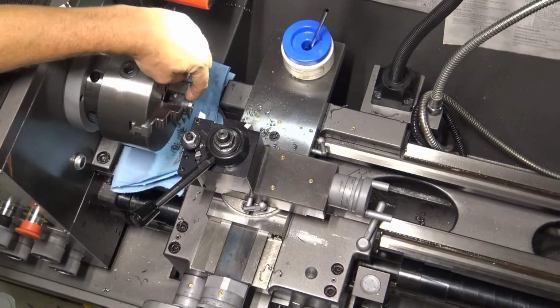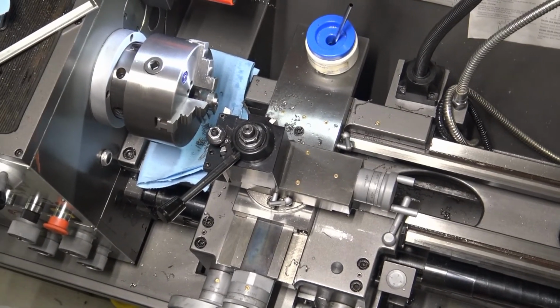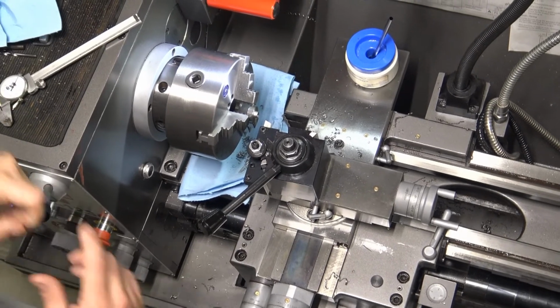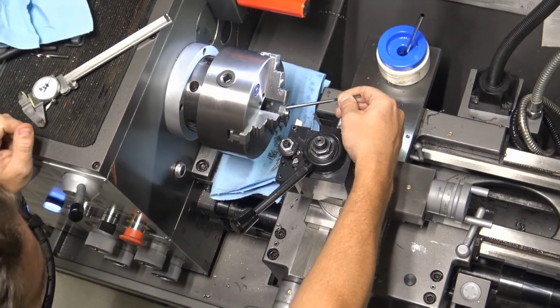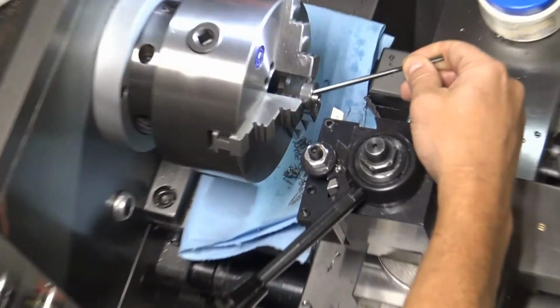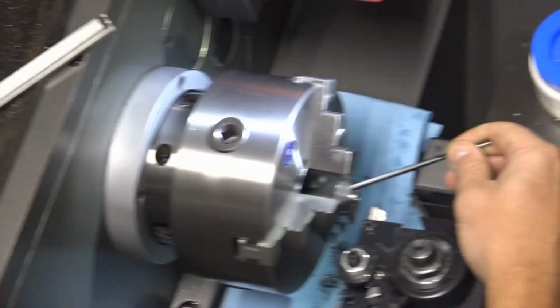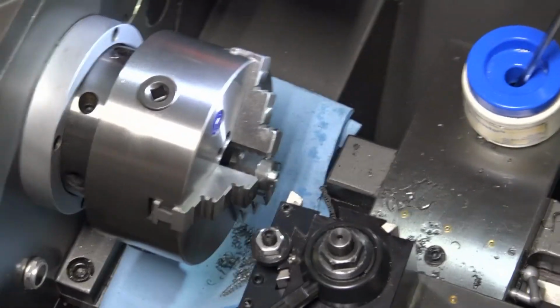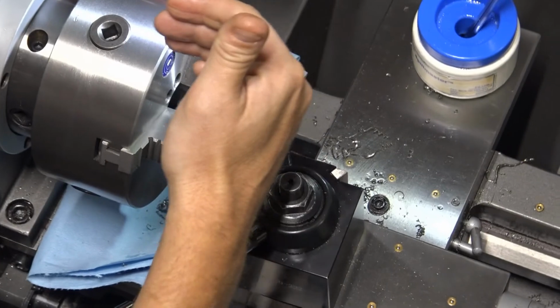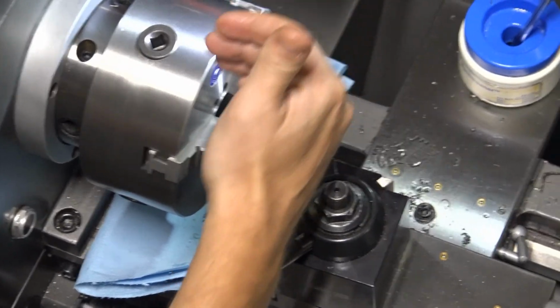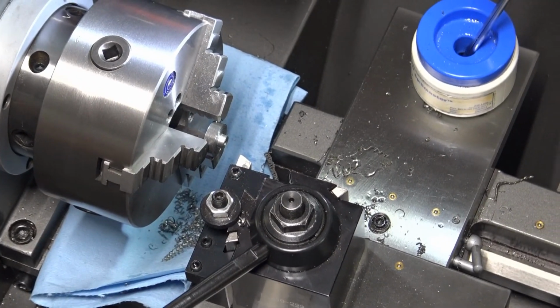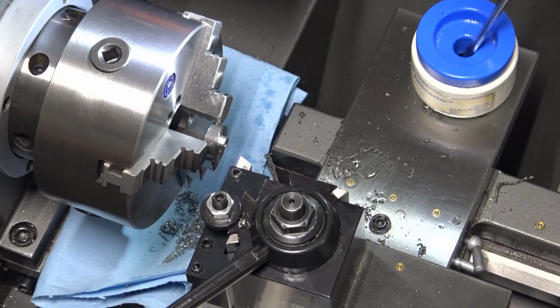It's going to be hard for you to see, but this face right here of our flywheel is all jaggedy right now. So when we go in 190, we're going to cut underneath that jaggedy surface, and as we pull it out straight, it's going to smooth that surface right back out.